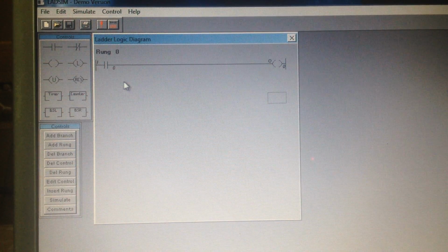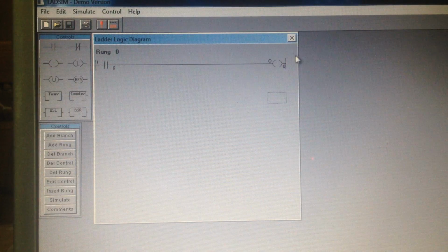So how will this work? This whole assembly is called a rung. This is the live wire, and this is the neutral wire. For any device to be operated, there must be two connections, one from the live wire and one from the neutral wire. In the path of the live wire, there is a switch, so only when you press the switch will it get the live wire connection, and neutral is already attached to the output. This output is symbolic, but in real hardware cases, it might be a motor and so on.